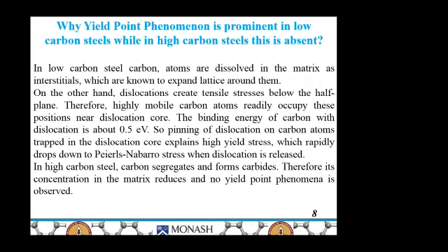In high carbon steels, carbon segregates and forms carbides. Therefore, its concentration in the matrix reduces, which means carbon will not be available for pinning of the dislocation. So that's why no yield point phenomena is observed.